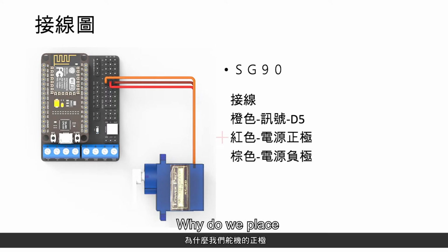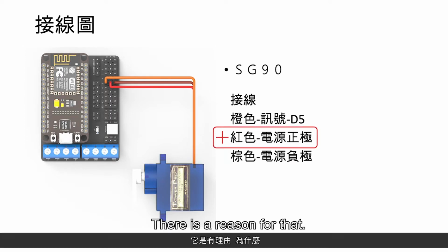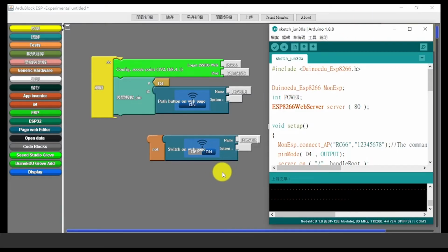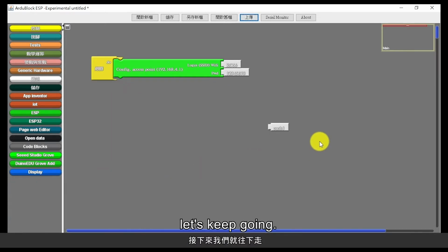Why do we place the positive terminal in the middle? There is a reason for that. Because if I plug the servo's wire in reverse, the servo won't burn out. After you have completed the wiring, let's keep going.